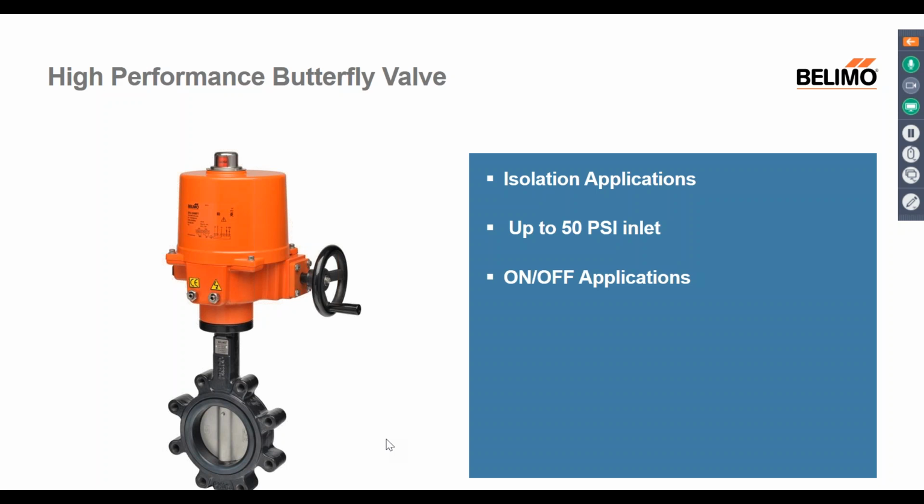Again, this one you got to be careful with. This is a high performance valve. If you needed a steam isolation valve to do a changeover system, this is a great selection because it's bubble tight. It closes off very tight. It's all Teflon trim, Teflon seats with stainless steel trim. So it's a good selection, but only for isolation.